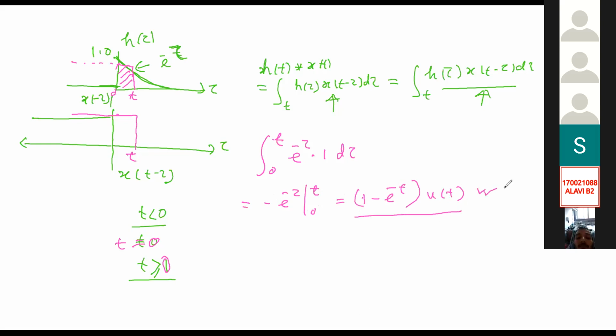Are you seeing this for the first time? Because you already know that if we apply a DC voltage across the capacitor, your capacitor voltage vC(t) is simply equal to magnitude E0 into 1 minus e to the power minus t divided by RC, isn't it? The u(t) must be there because we applied our E at time t equal to 0. So other than your signal with unit step, if you have a magnitude E0, then that equation can be generalized in this way.